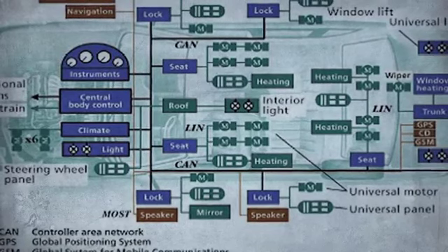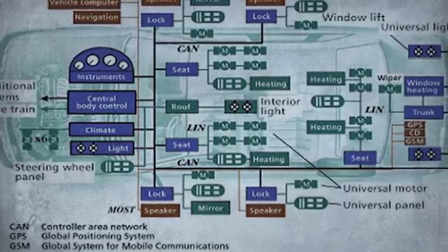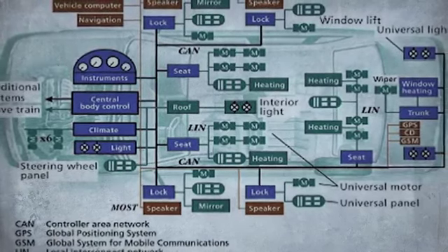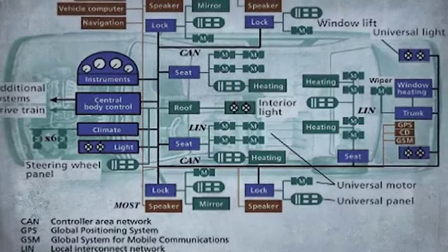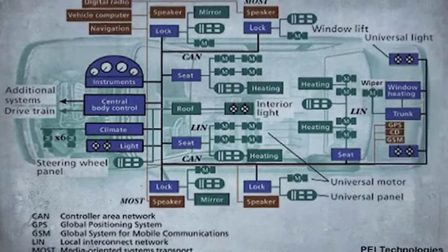This bus network is basically a network that runs through the middle of the car, and all the components that need to talk on that bus attach to this bus. This greatly reduces the amount of wiring and cabling you need for a vehicle, which cuts down costs and even weight, which improves fuel efficiency.